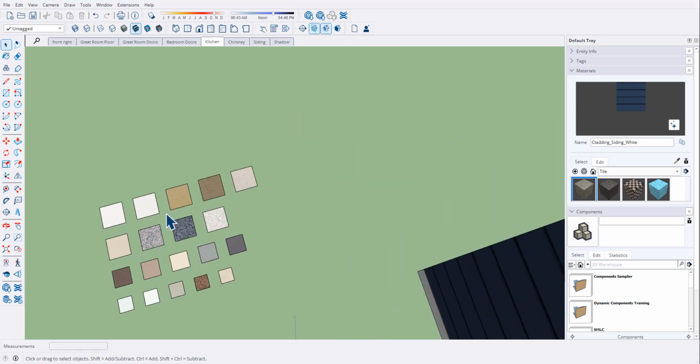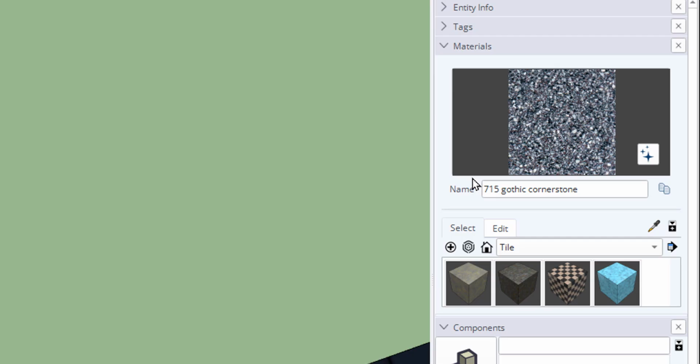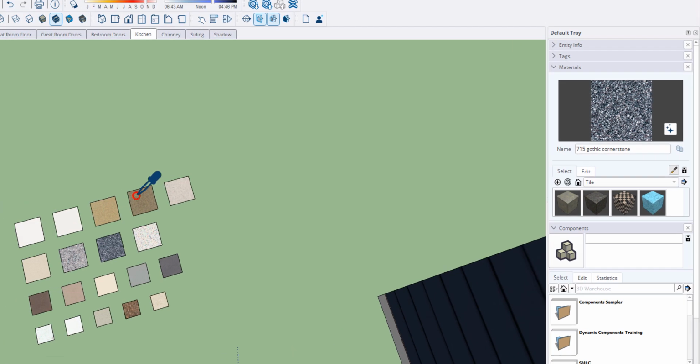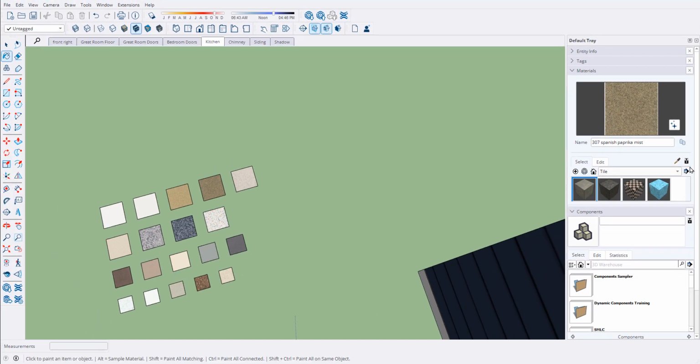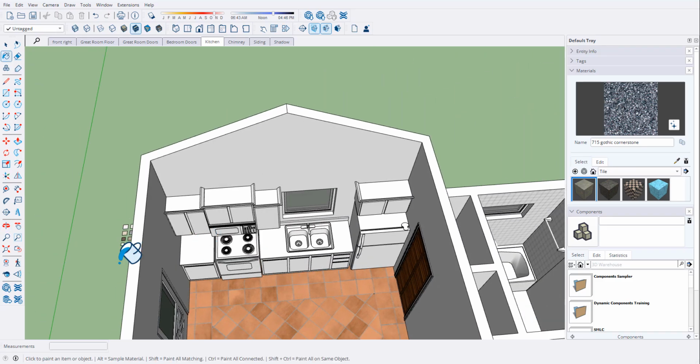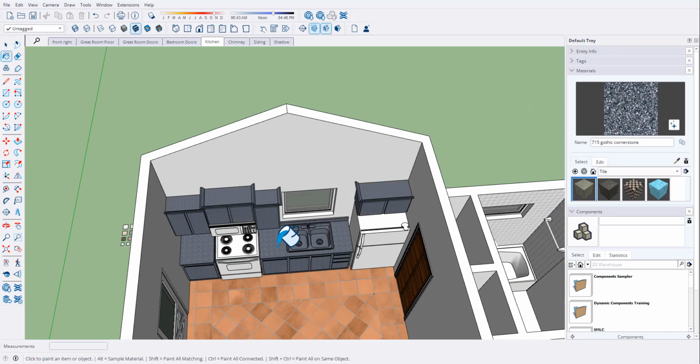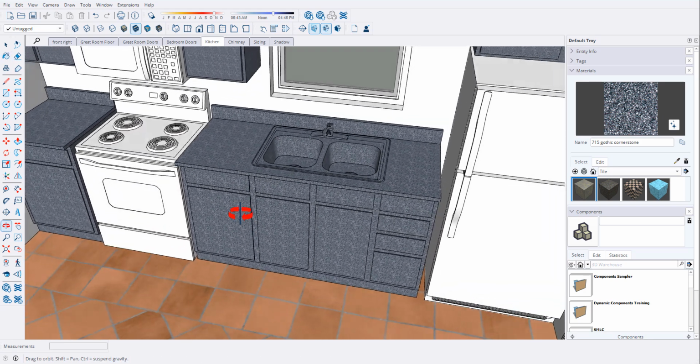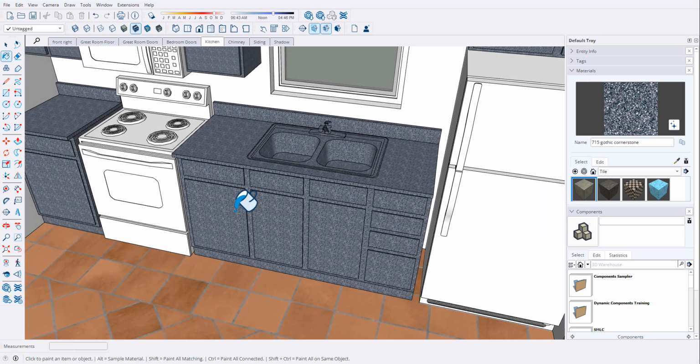If you scroll up on these, we can use the eyedropper tool and click on the surfaces, and you can see the model number and the name of that particular Formica product. And that's one great advantage of using existing materials. You know that that color exists or that pattern exists somewhere. Well, I'm going to say I'm going to paint it this blue. Let's say we want this particular color on our countertops. So scroll out, and if I click on here, look what happens. Everything gets covered. And that's not what we're talking about. We're not using that Formica on all the surfaces, just on the countertop.